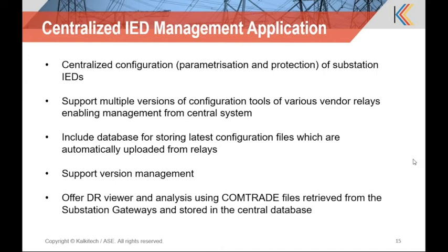It is centralized, and this is a centrally installable software, so it can have a server installed at the center and multiple clients. In the server you can map this to the electrical hierarchy: region, substation, and under the substation the feeder, and under the feeder the IED. You can link a tool to the IED, and once you click on that feeder, the corresponding tool will be launched with the latest configuration file. You can retrieve any previous version of the configuration file and do the management. So that is the basic principle.